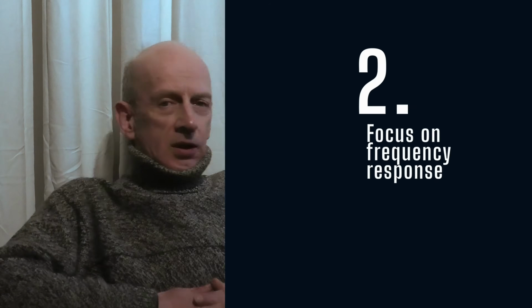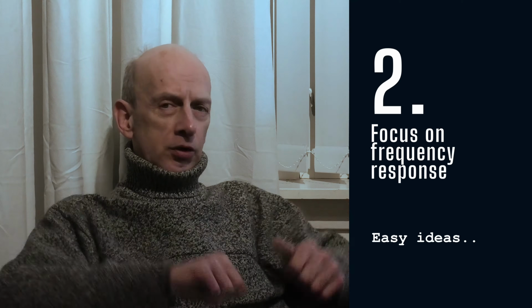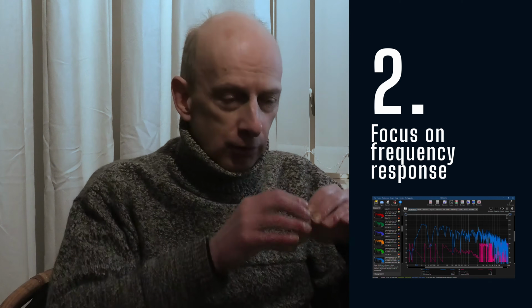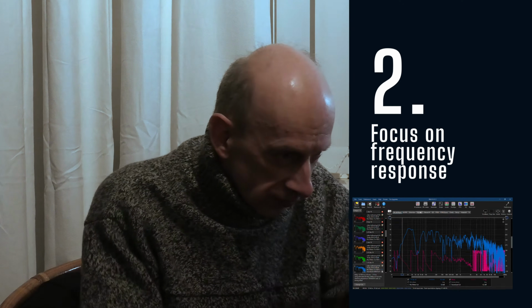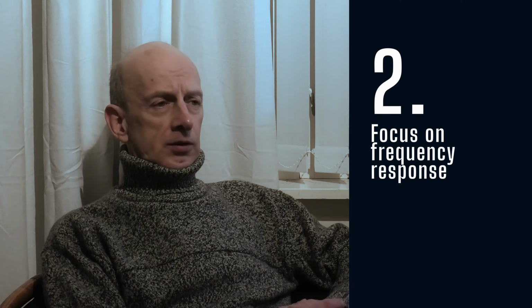Number 2, focus on frequency response alone. That is very usual. You see, they have set up the REW measurement, and they have a microphone, and then they have the frequency response. And then they use a magnifier and zoom in to see all the wriggles. This doesn't work. We need to look at resonances and the time domain. That is where the secrets to good sound lie.